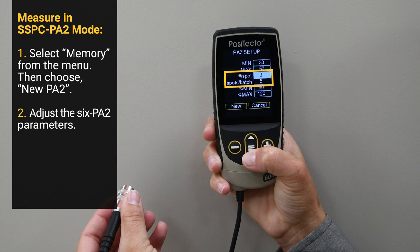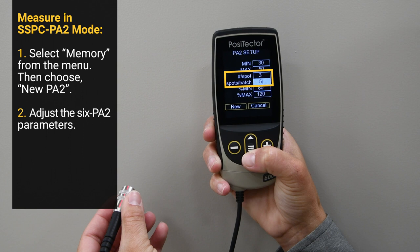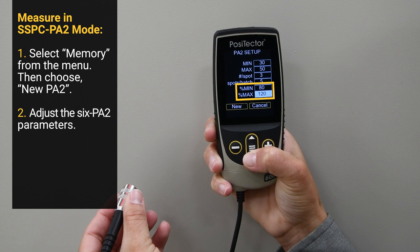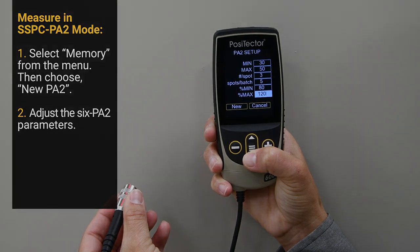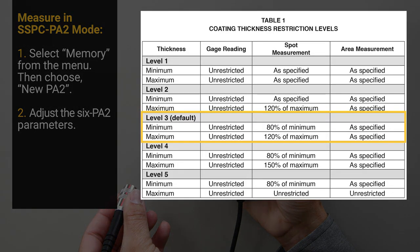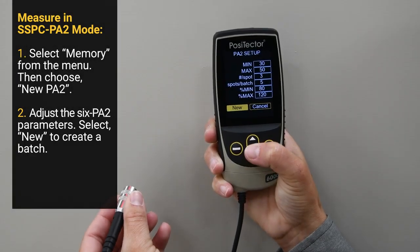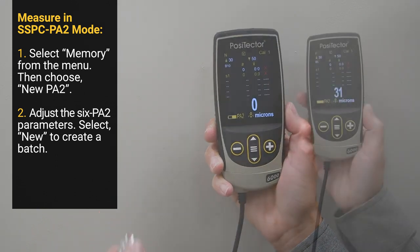The number of readings per spot and the number of spots per batch default to 3 and 5 respectively, as specified in SSPC PA2. The % minimum and % maximum options determine the allowable limits for each spot reading and are preset to the default Level 3 restriction level, but can be modified according to project specifications in Table 1 of SSPC PA2. Once all of the parameters are set, select New to create a batch.